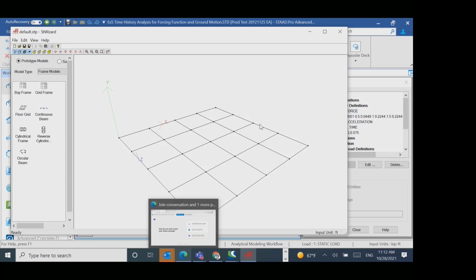Supports, the most important part in lifting, because you define the supports like lifting points. Usually they are defined as pinned, but if you consider, according to your criteria, that it's not exactly pinned, you can use a spring. But this is the third step and very important.